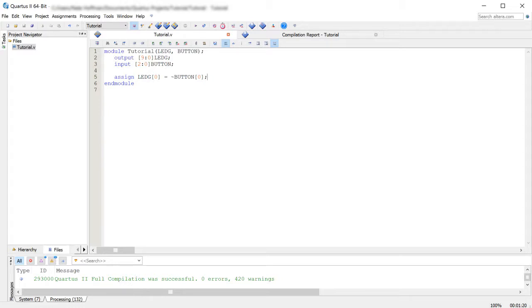and let's create a new circuit. For this, I'm going to be creating a temporary variable, you can almost call it, if you're familiar with other programming languages. But essentially, what we're going to create is a wire. And a wire can be used similar to an LED or a button or an input or an output, except you can both read and write to it, and it's internal, so it doesn't connect to anything outside of your circuit. So let's create just a wire, and we'll call it